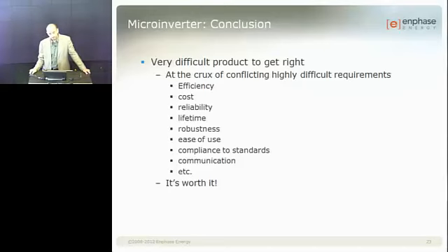So how did you do your accelerated lifetime testing, given that you guys haven't been in business for 25 years? We have a very large building filled with temperature chambers and humidity chambers, and we just cycle the heck out of them. It takes 3 months to do that. We have 3 different types of tests, actually 4. We operate the unit at full power, 85 C ambient, under high humidity conditions,